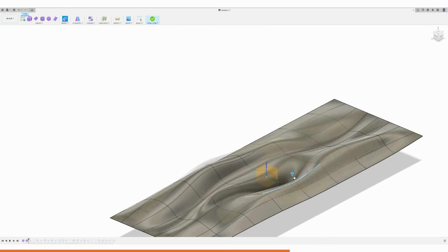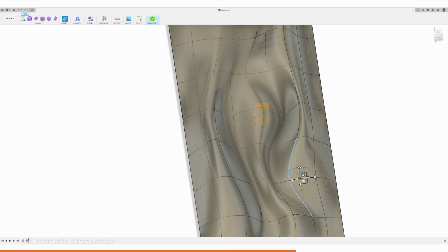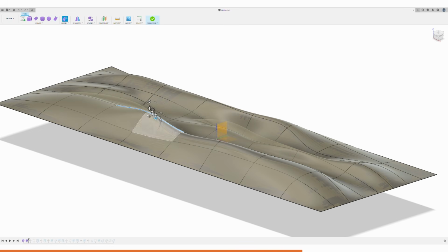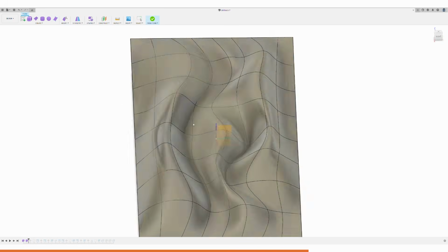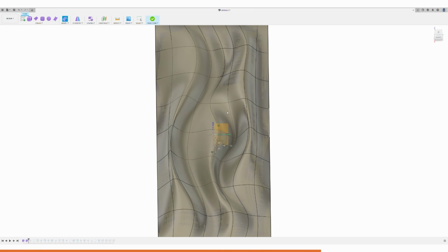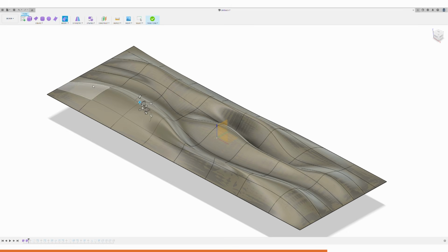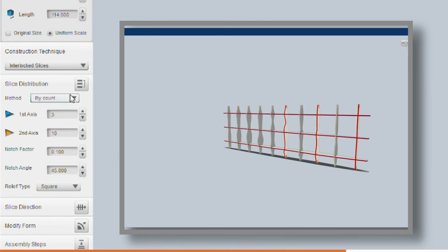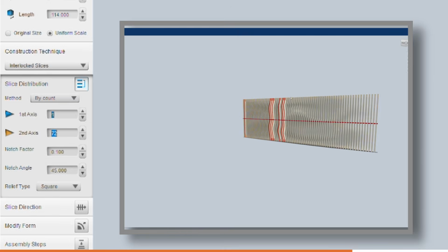This parametric design process is super cool because it allows me to do the artistic elements manually in Fusion 360. There's a bit of artistic touch required to get the shape of the wave correct, and I spent a good deal of time playing around with the wave surface and just getting it exactly how I wanted. But once I have that wavy surface designed, creating all those individual slats and designing those would be an extremely tedious process. But using the parametric design software, I'm able to generate all those slats automatically in less than a minute, when it otherwise would have taken hours and hours to do manually in Fusion 360.